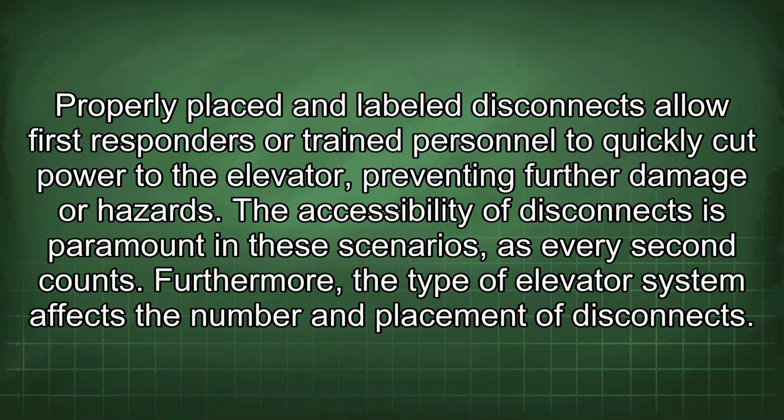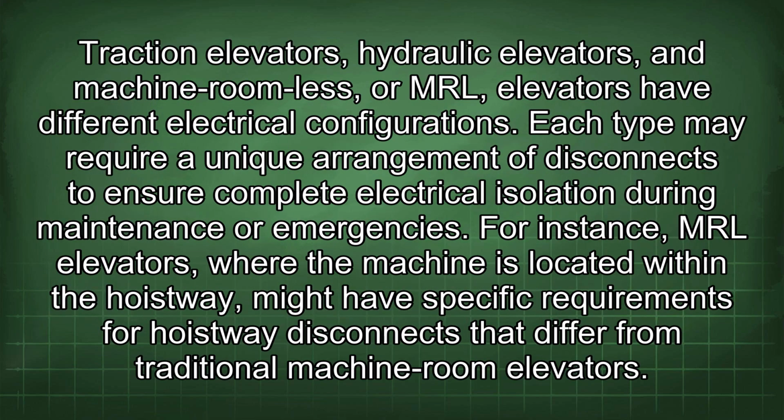Furthermore, the type of elevator system affects the number and placement of disconnects. Traction elevators, hydraulic elevators, and machine room-less or MRL elevators have different electrical configurations. Each type may require a unique arrangement of disconnects to ensure complete electrical isolation during maintenance or emergencies. For instance, MRL elevators, where the machine is located within the hoistway, might have specific requirements for hoistway disconnects that differ from traditional machine room elevators.